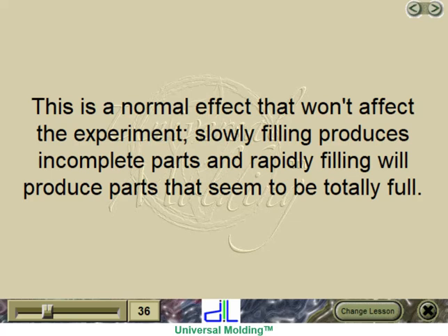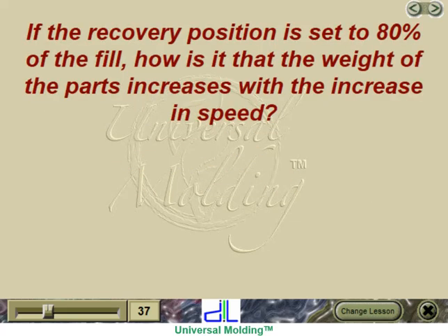Slowly filling produces incomplete parts, and rapidly filling will produce parts that seem to be totally full. If the recovery position is set to 80% of the fill, how is it that the weight of the parts increases with the increase in speed?